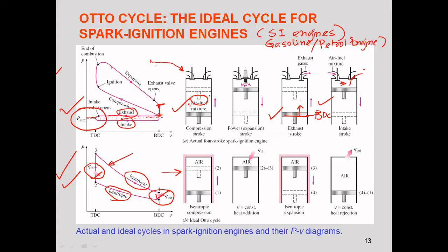Therefore, as the piston compresses the exhaust gas, the extra gas at extra high pressure, meaning a little above atmospheric pressure, will now be rejected to the atmosphere, because the pressure due to the compression has made the pressure inside the cylinder a little above atmospheric. So that pressure differential causes a flow.